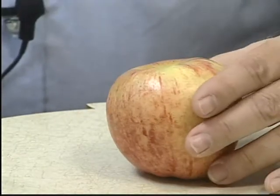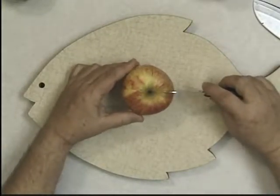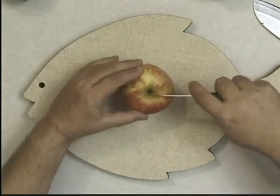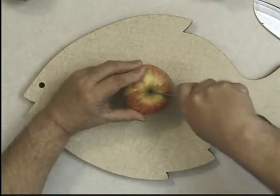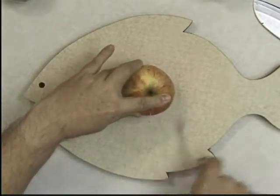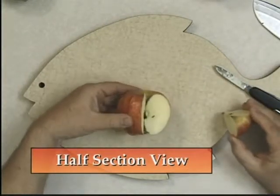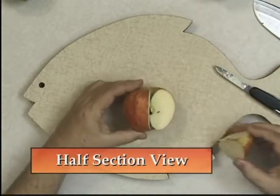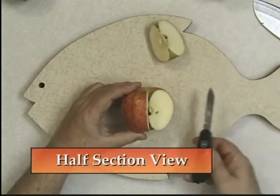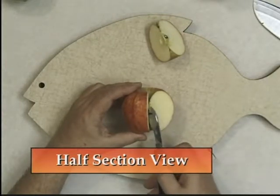In this case, I'm going to use my trusty Swiss Army knife and I'm going to make a front half section view. And a half section view, remember the full section view I cut fully across. The half section view I'm only going to cut halfway across and then I'll cut out. And here I have a top view, and if I take this part out, you see that I have a half front section view. Now you say, but you cut a quarter of the apple out. Don't be confused by that. I cut halfway through the object and then out, and it reveals what's inside the object.